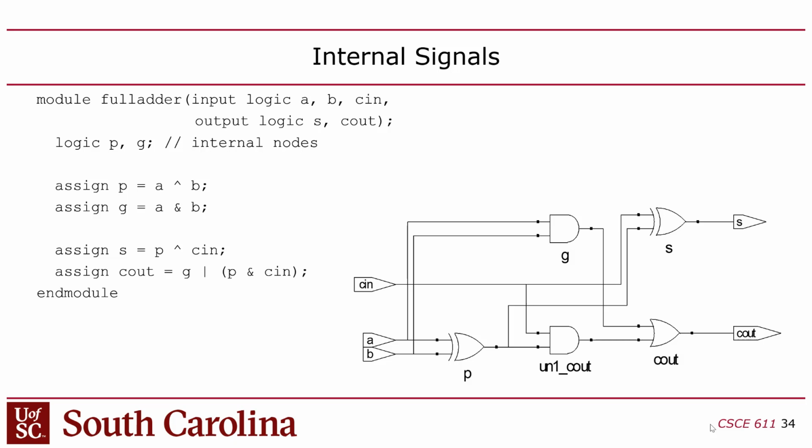Yes? But isn't, for example, delay something that can be synthesized like a stack of inverters? If there is an even number of inverters, then you get your original signal and you get the delay. Yeah, like a ring oscillator. Yeah, I've never tried to do that, but that would be technology dependent, right? So if you built a ring oscillator on an FPGA, which I've never done, I don't know how that would end up. I've done it on an ASIC before, and I've done it using SPICE, which is transistor level circuit simulation.